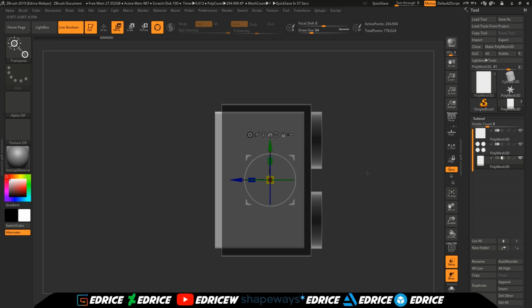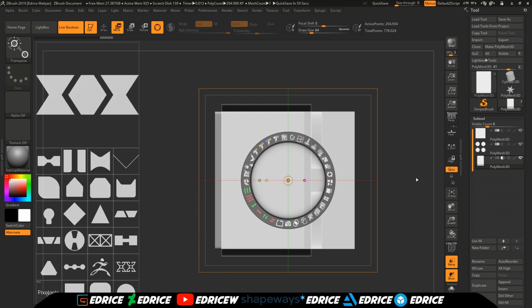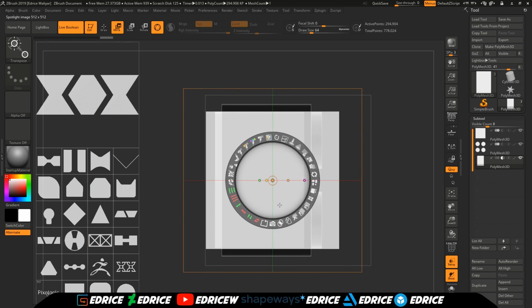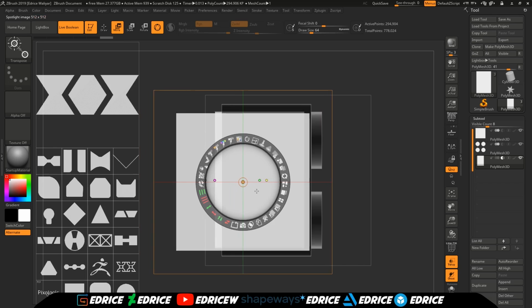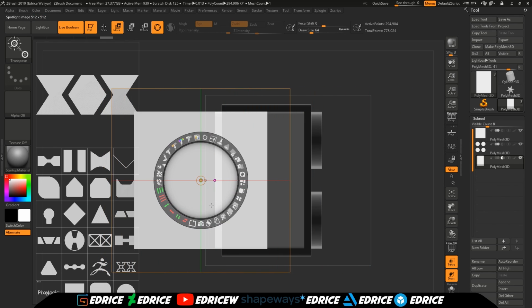And now, just to simplify everything for us, we are going to do the same thing again, but this time we're going to Shift Z, Z, and we are going to take this, and start to move it, holding Shift so we are aligned on the same axis. So you have axis planes on your alpha. You have this green and red line. So if you start moving and hit Shift, it will conform to that axis. We're going to move this down